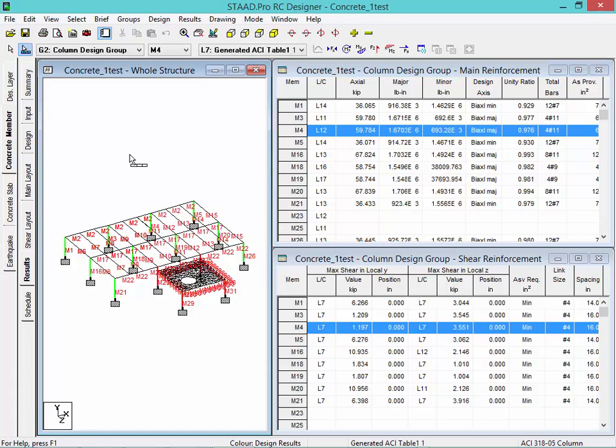Now for this particular model, we did have several different concrete columns that have failed the design code check. We have a couple different options here. The first option would be adjusting the column design brief. If we feel that maybe some of different design parameters could be assigned to these particular columns that could maybe get them to pass the code check, we can go ahead and adjust those. These might be things like different bar arrangements, or also maybe adjusting the concrete compressive strength.